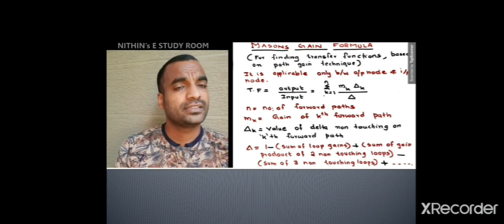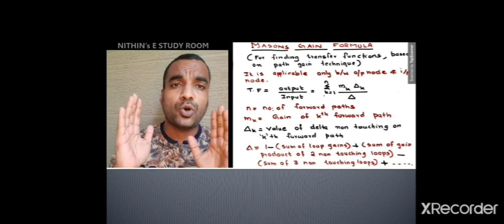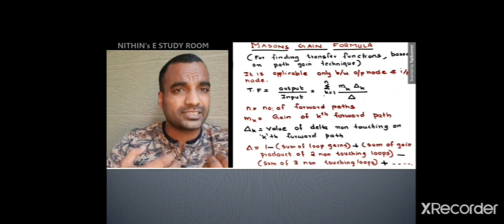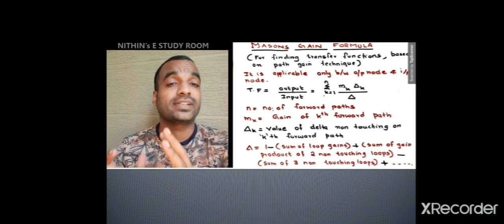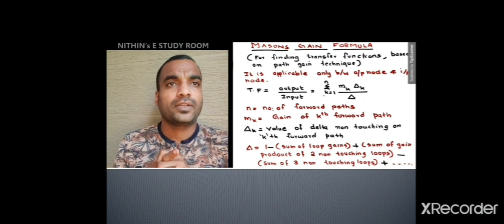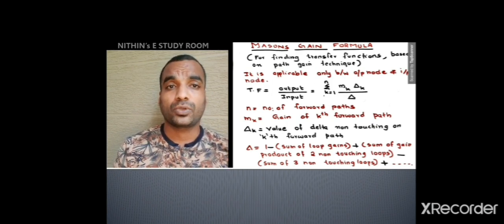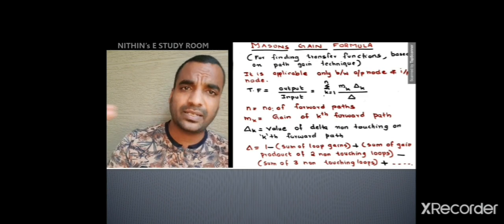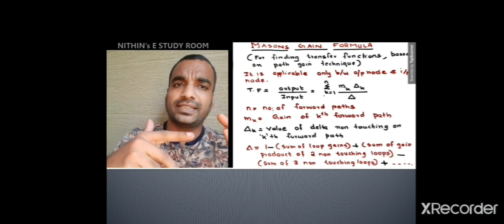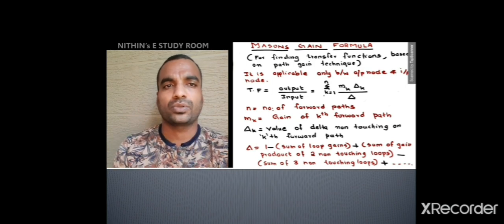So, in our case, we already know that x1 is the input node because from x1 all the signals are radiating towards outside. No arrow marks are coming towards x1. All arrow marks are going from x1 to the other nodes. So x1 is an input node. But by looking at the other nodes, we can see that they are neither output nodes nor input nodes, because considering x2, x3, x4, all the nodes are receiving some input arrows and sending some signals towards the output direction also. Both directions are linked with each node.